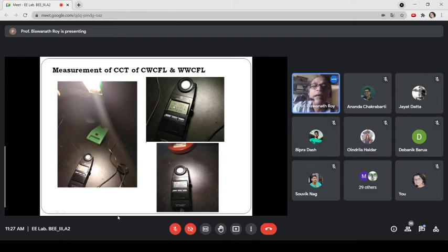Above, you can see EV written here, this is for illuminance. What is the lumen incident per unit area? Lux, LX, small l, small x. So this value reads the energy incident over the sensor per unit area. So if the sensor is fully covered by this cap and we switch on the instrument, the value appears here as 0 and starts blinking, indicating that zero correction is done.